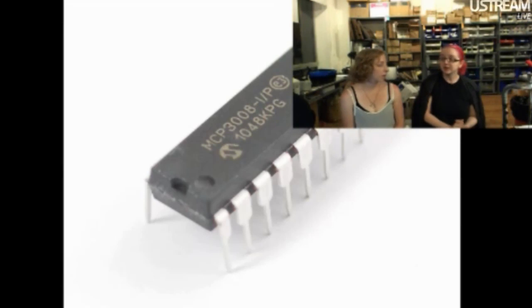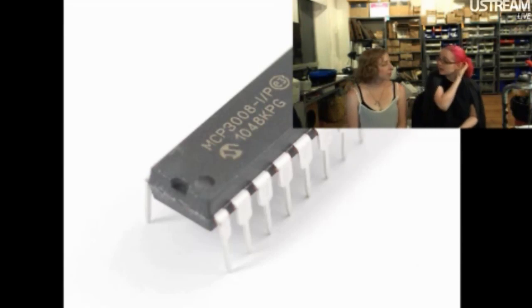So now you can use pretty much any sensor, because the Pi has I2C and SPI, and now this is an easy way to add analog. Sweet. All for just a chip. It's only a couple bucks. It's super easy, and if you want more, add another chip, and you only need another CS line. So you can add another 8 analog inputs, and it only takes one more pin.